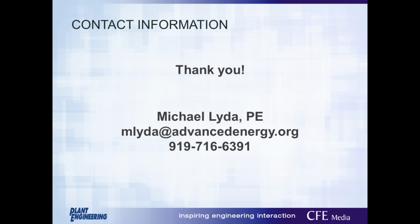Another question, inverter duty versus inverter ready motors. I am finding engineers writing specifications that are sometimes conflicting. Yeah, this is an interesting question. Inverter duty, when we talk about motors that can be operated with a variable frequency drive, that's where we talk about inverter duty. They will be valid to run the motor across a full speed range listed on the motor nameplate at whatever variable torque range listed on the motor nameplate.